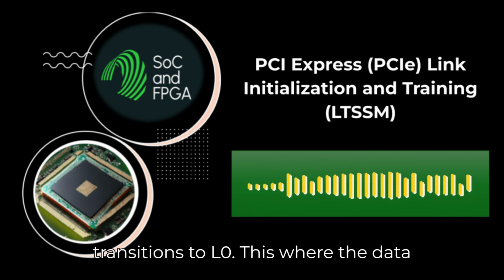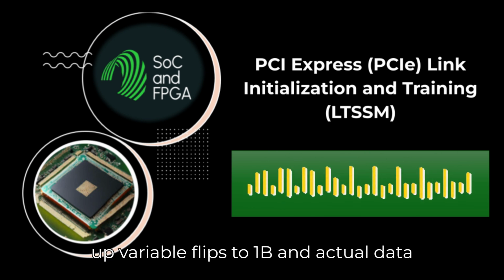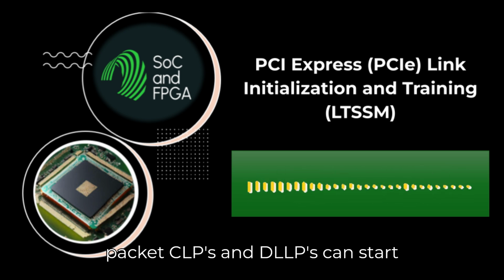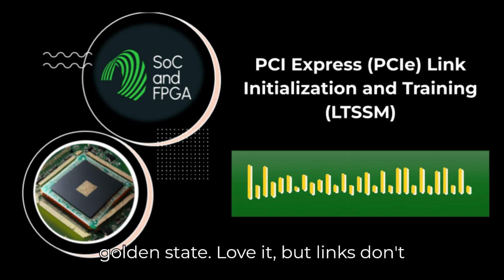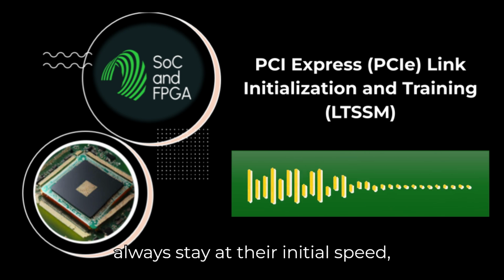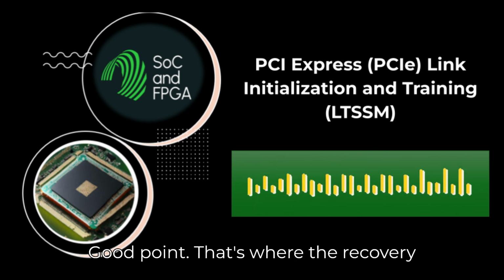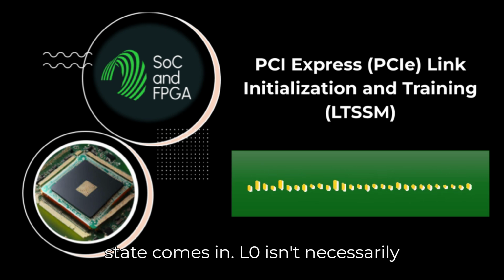This is where the data link layer finally comes alive, the link up variable flips to 1b, and actual data packets, TLPs and DLLPs, can start flowing. It's the golden state. The golden state, love it, but links don't always stay at their initial speed, right? What if they want to go faster? Good point. That's where the recovery state comes in.